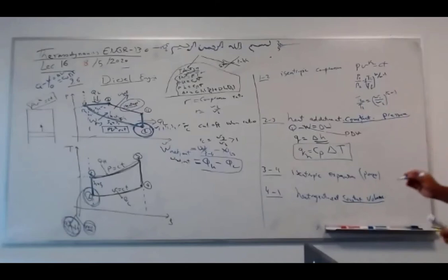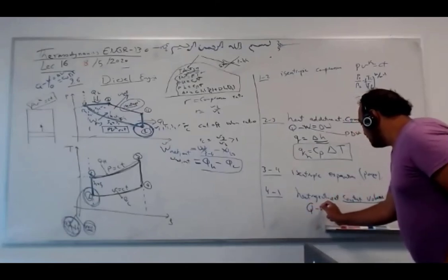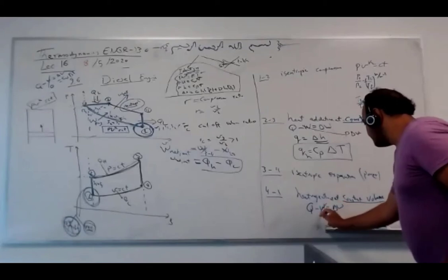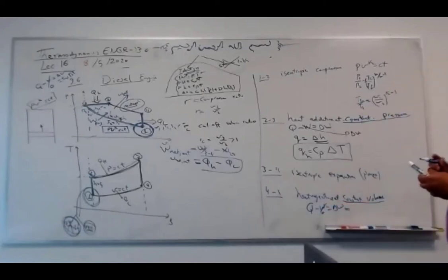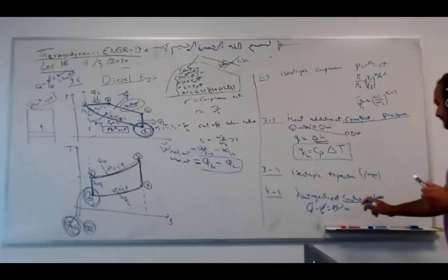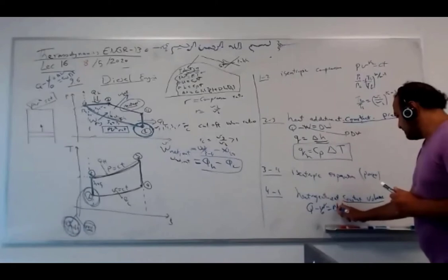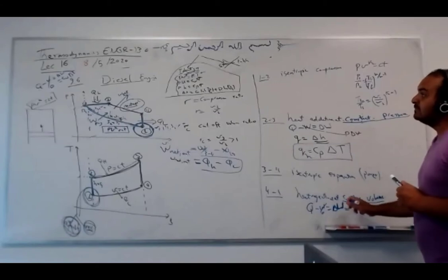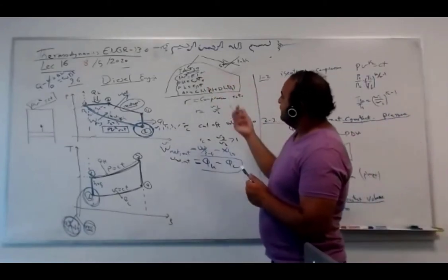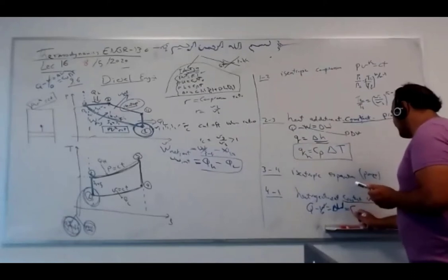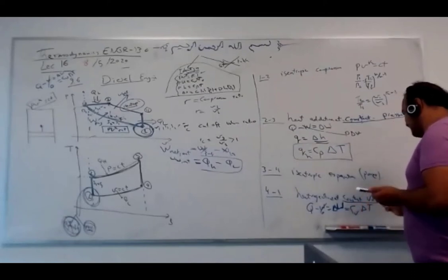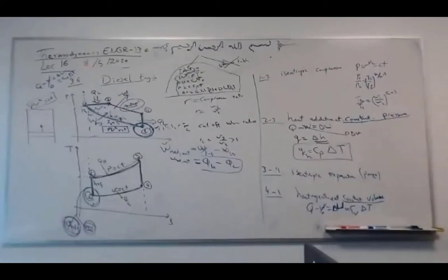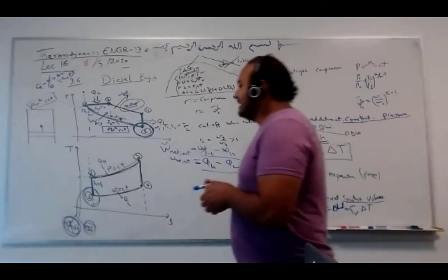There is no W because it is constant volume. So just Q equals delta U. Which means what here, guys? If I want delta U for an ideal gas, what is this? CV, sorry. CP is for enthalpy, CV is for internal energy. We discussed this many times when we talked about ideal gas in chapter 3.